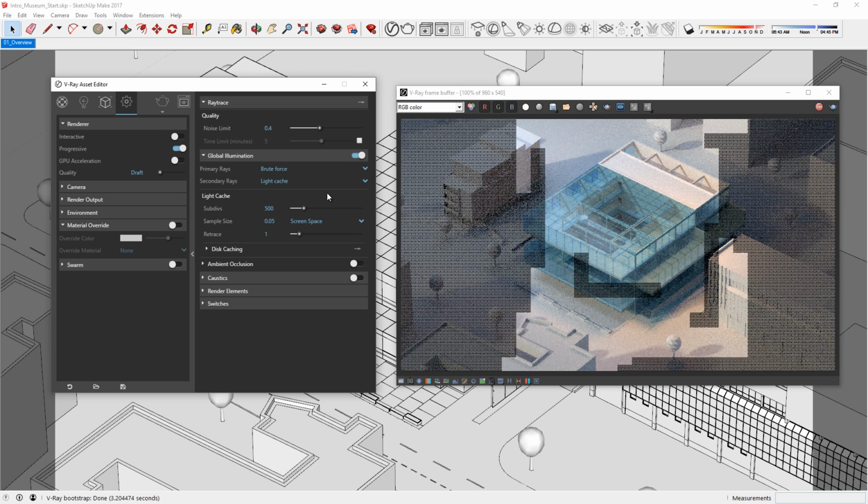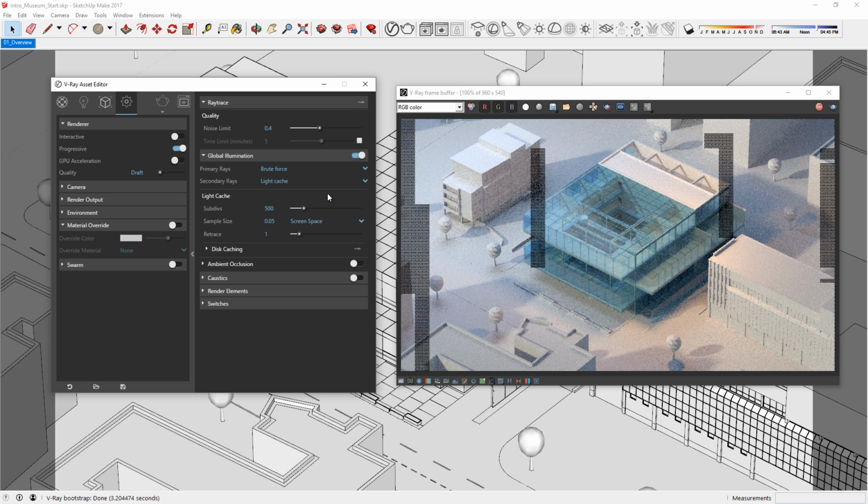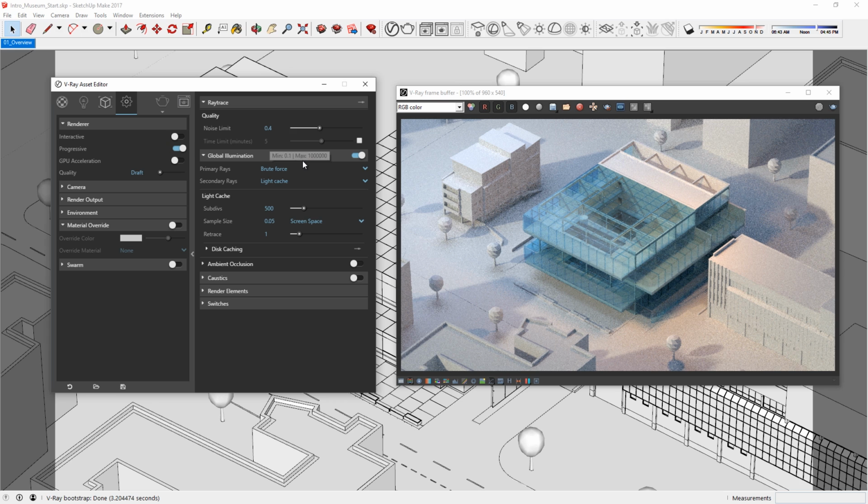Great thing to know about the progressive rendering is you can also control it by time if you like. From enabling the option here in Ray Trace, where you find some additional settings for rendering, you can control progressive rendering by time. So if you have just 2 minutes, you can set this one to 2 minutes. It will give you the best quality for that time. But in our case, we use the draft rendering preset, and here is our result.